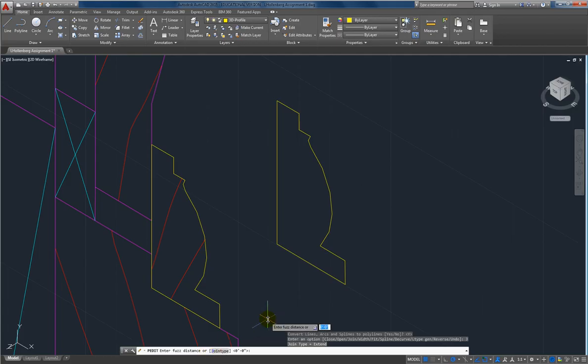The fuzz distance is the distance that these two things, as you zoom in infinitely to it, are apart. They're apart by fuzz. Okay? Do you understand what fuzz is? Like stuff that comes off your shirt. It's really thin. So it's the fuzz distance. I know this is bizarre, but so every intersection has to have fuzz? No, typically not. But if you draw sloppily, you might get fuzz. So if you're not using your endpoints properly or you're not being careful.